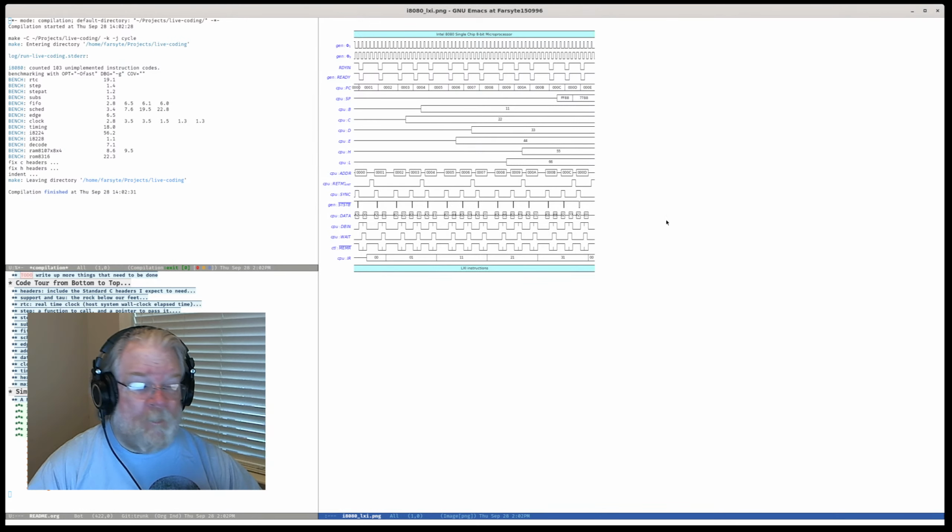So this is what the timing diagram looks like for these LXI instructions. We got our NOP in here. We got our LXI, which has 3 machine cycles. And we get 2, 2 into C and 1, 1 into B. That's correct, so 1, 1, 2, 2. Same pattern for DE, same pattern for HL. And SP changes to FF88 and then 7788. So LXI is now working.